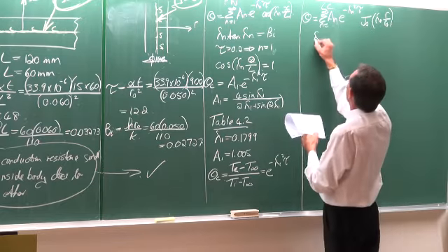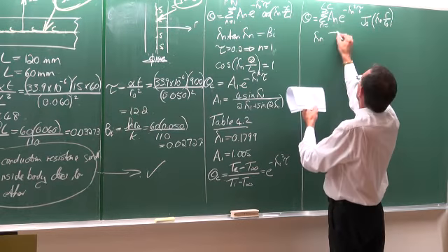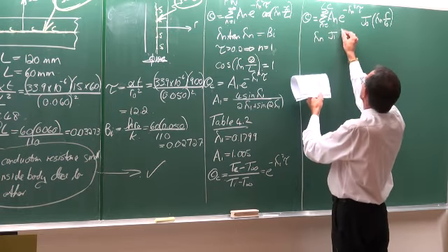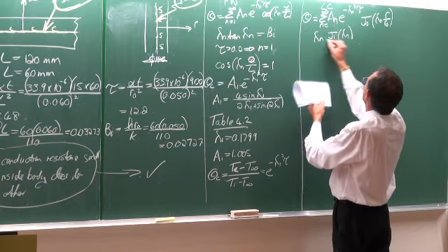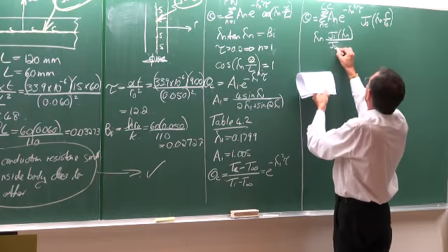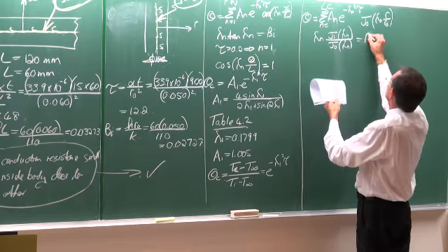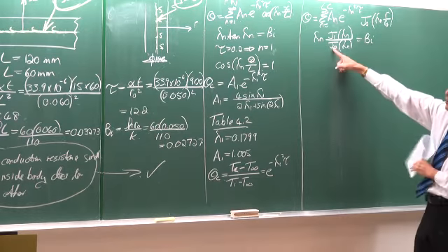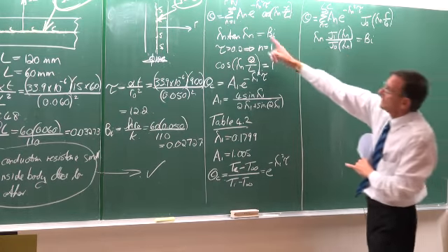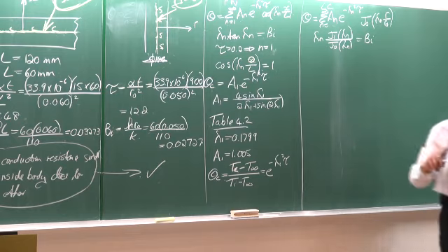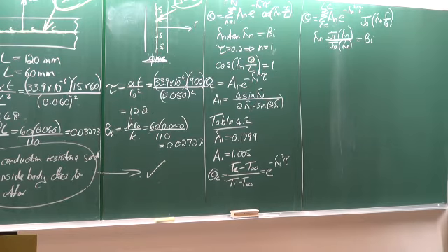And where lambda n multiplied by the first Bessel function J1 of lambda n, divided by J0 of lambda n, is now equal to the Biot number. So our roots previously were calculated with this equation, it is now calculated with that equation.